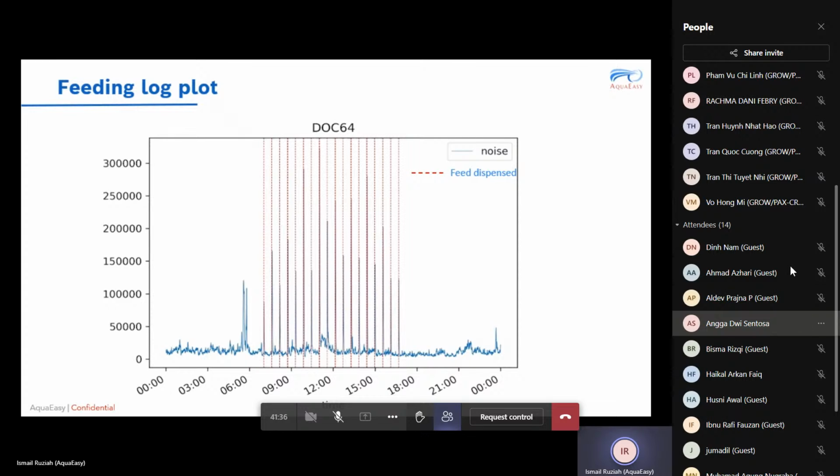You can take the average of the feed dispensed, and there's a table. The table looks something like this, an Excel sheet. For feed type A, maybe 33 seconds, how many grams and how many grams per second? You repeat this 5 times or however many times, and you get the average. So this is basically the process of doing the feed dispense tests.